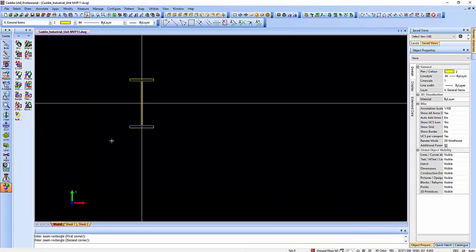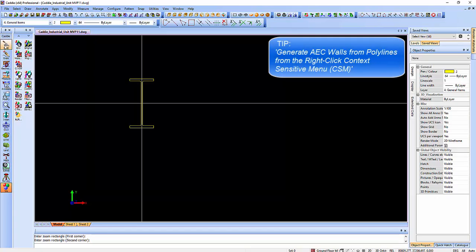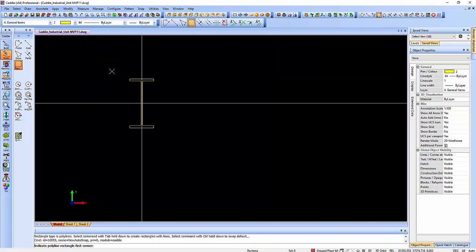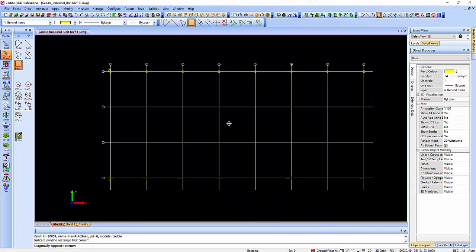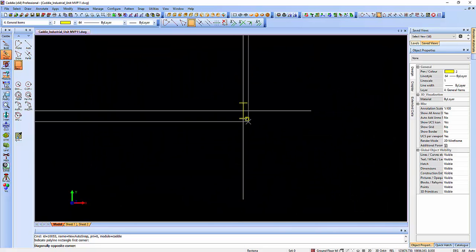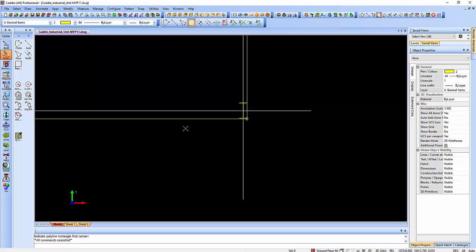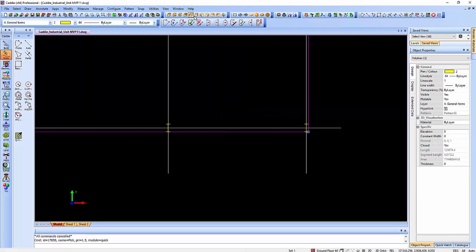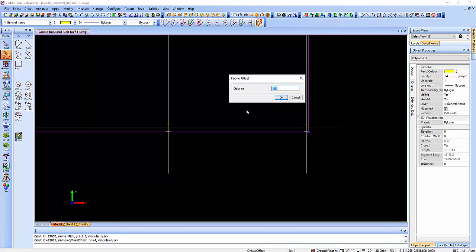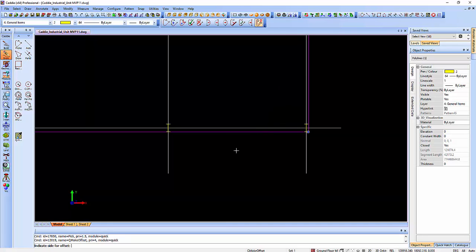We're going to do these from Polylines, so we could go to the build commands, the draw command and so on, but if I just go to something as simple as a Polyline, we'll choose auto snap, pick on the corner there, drag down to the other corner, and place our polyline in. Now, there's our polyline. Under the context toolbar, we have offsets, so I know that I need an offset of 135 till we get to the cladding, so purlin will be and so on, so okay that.